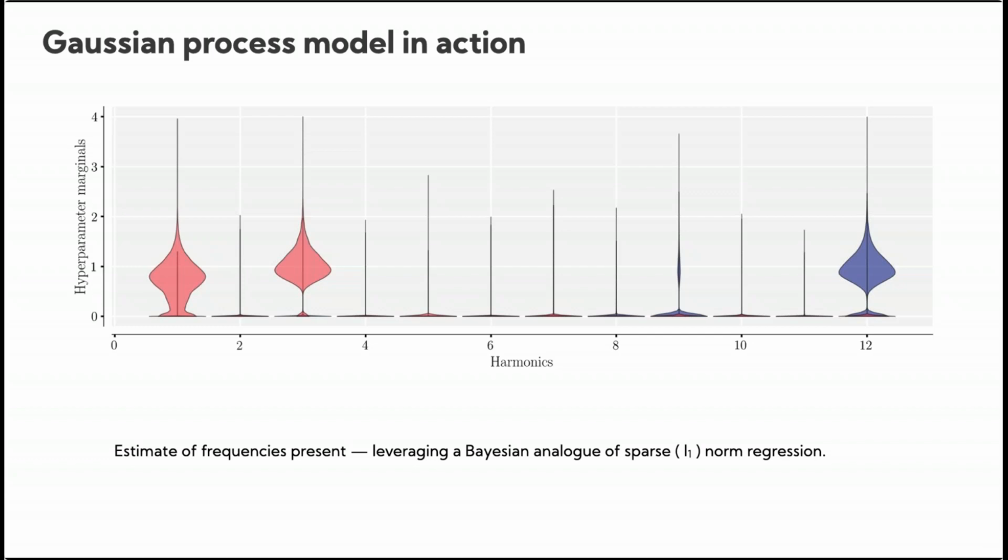But in an axisymmetric model, what you see is not directly the gradient of density. In 2D, you can integrate along the optical path. But when you are axisymmetric, you are crossing different density gradients, and then you have to take the log of this density, and then it's different to interpret your Schlieren. So I don't know if your technique could cope with that also.